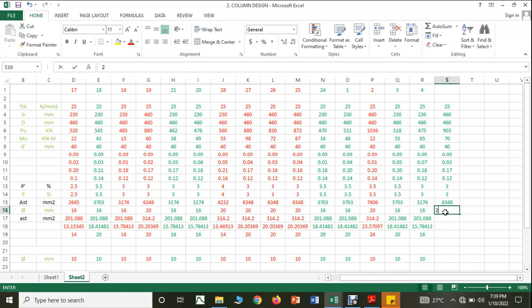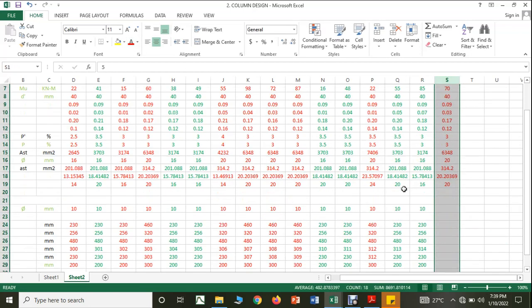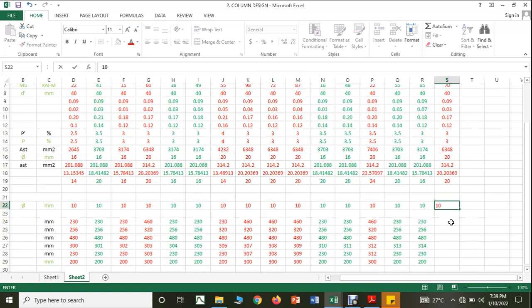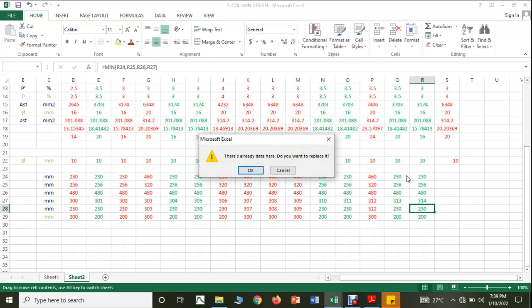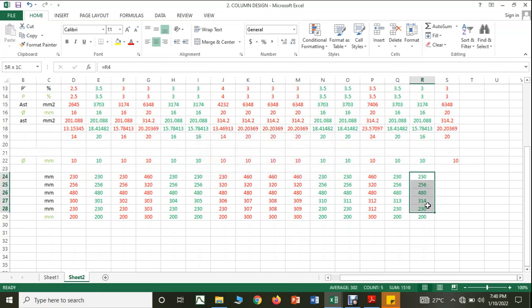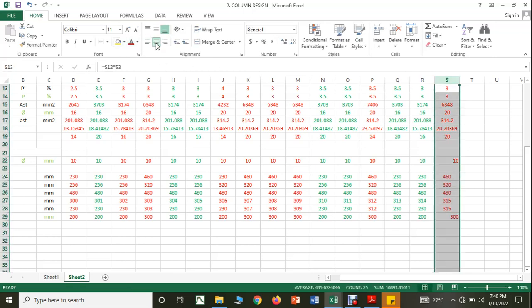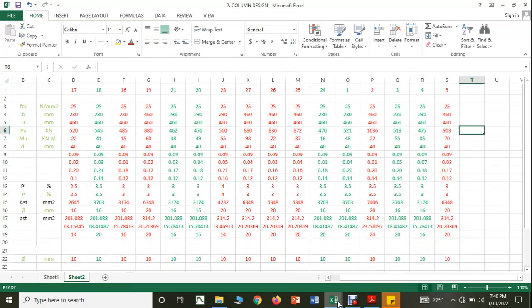Going to maintain 20 mm diameter rods. So this will be the total area of one rod. So I'm going to get 20 mm numbers. This is column number 5. I'll make it in the red color because I'm supposed to change it. So 10 mm stirrups. If I maintain 300 mm center to center, I have to make it red color. Yes, that is column number 5.